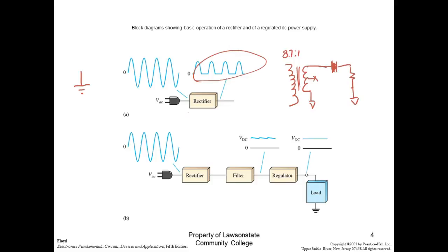So that's a common, because I lose my ground. Even though when I plug this into Alabama Power, this side right here is connected to ground if I don't break off the center lead, as soon as I come through that transformer, ground's gone, because that energy is transferred magnetically. So if I wanted the secondary of a transformer to be grounded, I've got to ground it. Y'all understand that? So this is why you've got a ground.